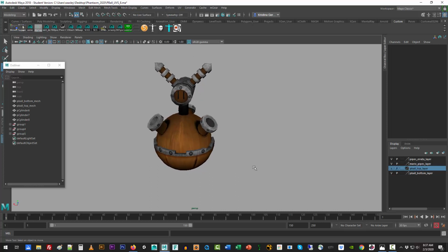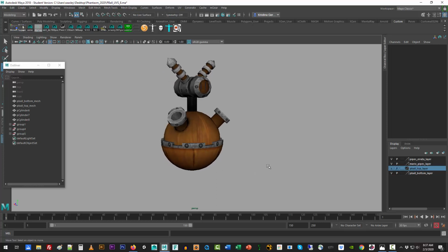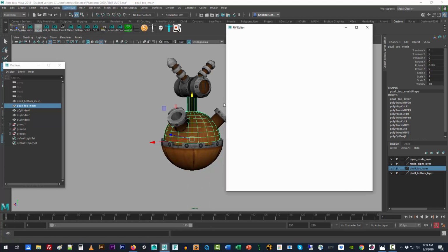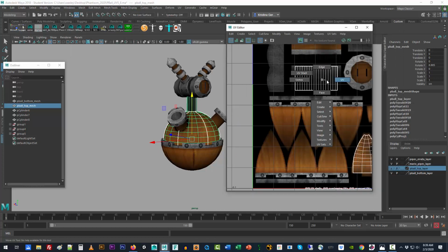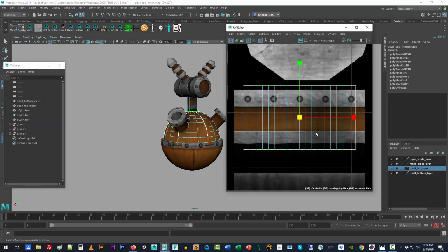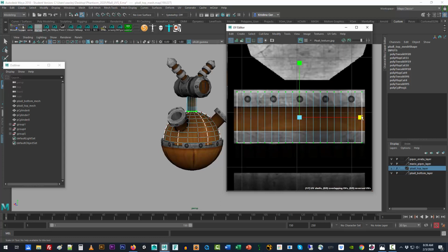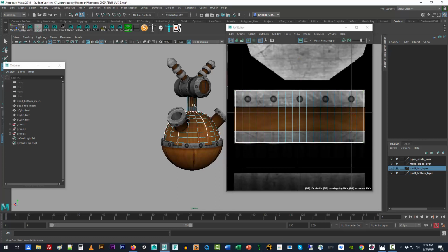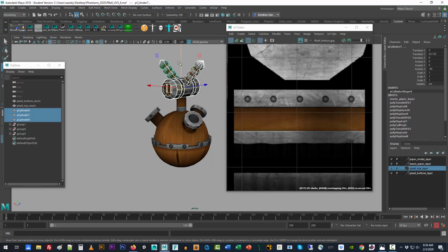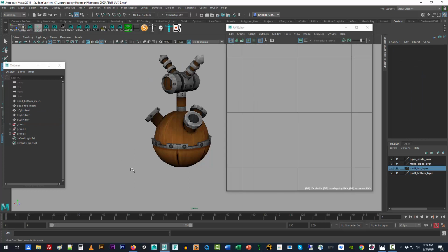And just as a flourish, let's improve the neck slightly on this, just as the last little coup de grace of this object. So let's go. Jump in, bring up your modeling window or your UV editor window, and let's grab this and put this on a much more interesting surface on the texture, which is the one right above it. So massage this, and it's small enough that we can just do this interactively while leaving the window up, and you can drag it near the top, and there we are. It's slightly better looking. In fact, I'm so excited by this, I'm going to just raise it up to show that cool little neck. So there we are.